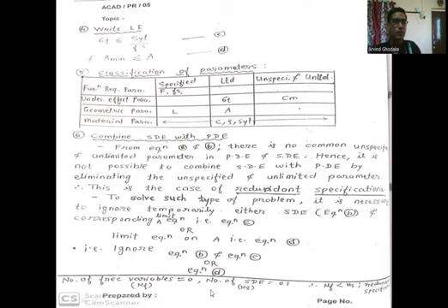So the functional requirement is the effect parameter, then geometric parameters and material parameters. Here sigma T and Cm are the effect parameters, geometric parameters are the length and area, and material parameters are the density, then cost and ultimate stress.